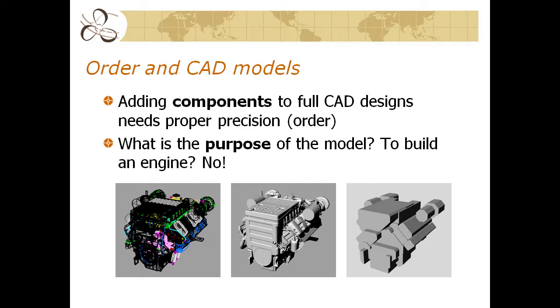Would you use this CAD model for a ship design? Of course not. Its precision is way too high, far too high to be useful for the purpose at hand. So we developed a little utility to simplify CAD models, from the very, very detailed component to finding an envelope, like in the second column, to creating what we call a prismatic element representation of a model, where all you need is the basic connection points. That's what you're after when you're doing ship design.